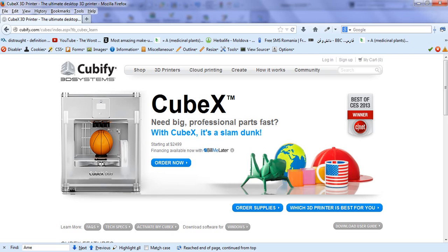In fact, when you go to their website, you see that they made this basketball, and even in the commercial it shows a basketball, perfect, color and all the lines. But I highly doubt that you can do something, or it takes really several tries to make it in that perfect scenario. But the problem with this is the printer actually. When you want to make different colors, it goes and makes it layer by layer. And if you have, for example, 3 different colors in one layer, for each of those spots with that different color, the jet has to go back, has to be cooled down, the other jet has to warm up, come and make that perhaps feature, and then go back, and it takes a significant amount of time.